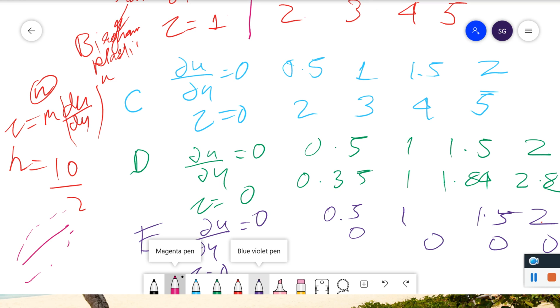So for C you can see that the shear stress is 0, 1, 1.5, 2. As the shear rate is increasing, the shear stress is also increasing. So it's clear that it's non-Newtonian. And since it is increasing with a decrease in shear rate, you can see this, C1 I will get, I think, so it becomes pseudoplastic. Wait, I will just explain why it is pseudoplastic.